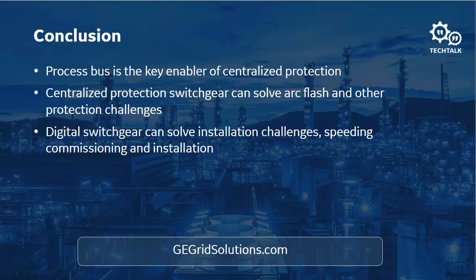What do I mean by latency? Is there an additional time adder on the process bus versus a traditional output contact or a traditional wired solution? There is a small adder. Usually that is around 4 to 5 milliseconds.